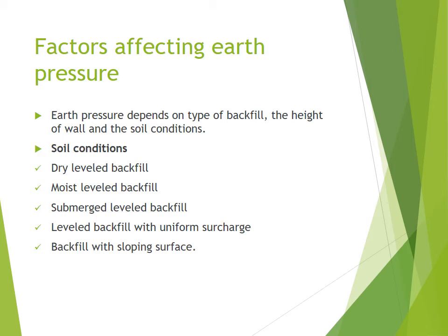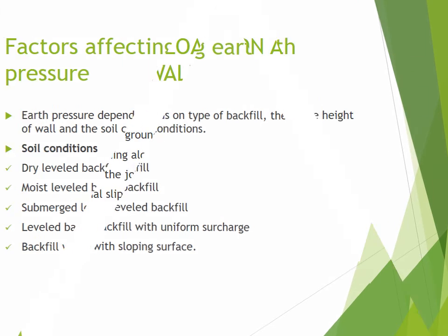Then we have submerged leveled backfill, which is maybe submerged in the water, then the water is drained at some times. Then we have leveled backfill with uniform surcharge, which is normally a backfill to the level of the wall, and backfill with sloping surfaces that can affect the earth pressure.